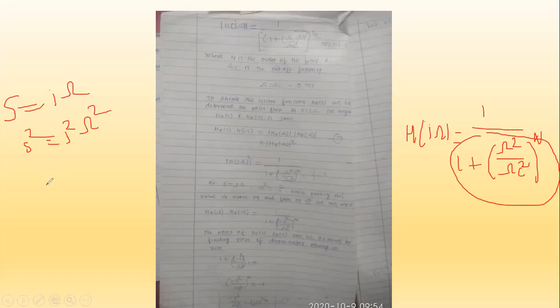It is nothing but minus 1. So analog frequency square is equal to minus s square. So this j square is representing a minus 1 term. So I'm going to substitute lambda is equal to minus of s square in this equation. So here this value I'm going to substitute in this equation. This is one equation.